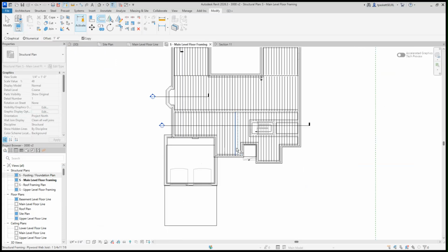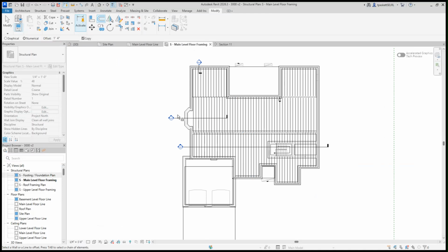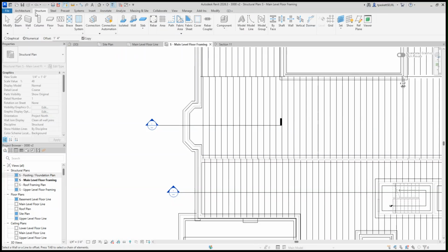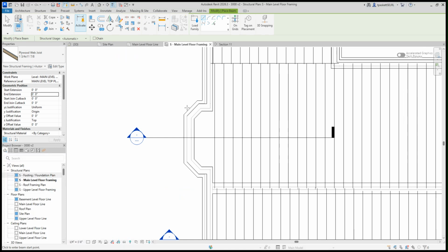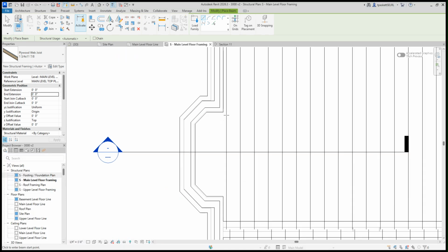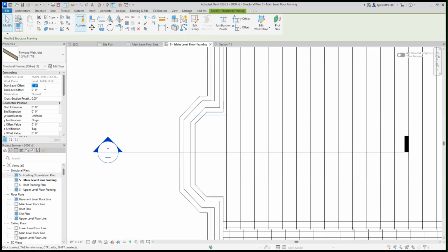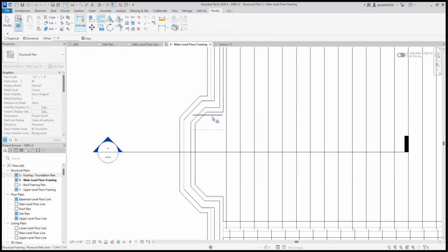That is the framing now for my main floor. We got this little bay here. Better put that one in. So I need to go structure, beam, still the TGI. I'm going to take it going this direction to the midpoint there. Again, verify my heights, offset heights. Control V there, Control V here. Do a little offset work and just marching along its merry way there.